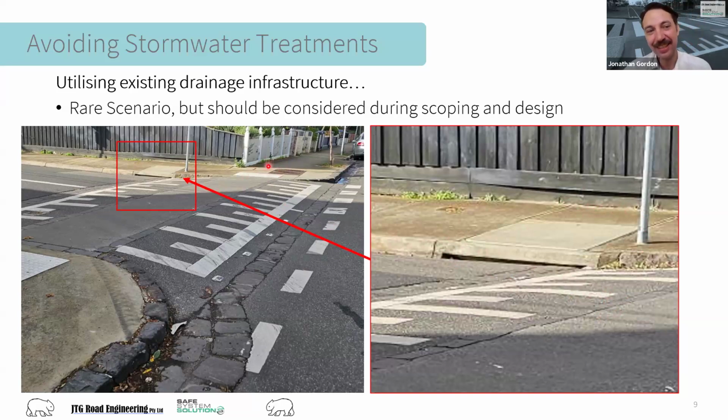And you'll find it's a disappointing feeling when you realize that a lot of the times these are positioned really close to an existing crossing, and when the ramp sections are constructed for our projects, these need to be converted to a junction pit, and perhaps another side entry pit is positioned prior to the toe. I'll be talking a lot about positioning of side entry pits and other drainage solutions shortly, so yeah, that'll be good for anyone interested in that.